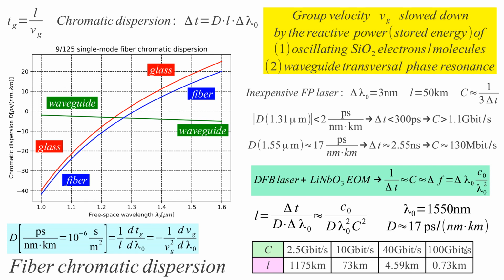And forget 100 gigabit Ethernet with simple on-off modulation. Here we cannot get to our receiver even inside the building. We may have more than 700 meters of cable inside the building. So here it's a real problem. Here we are still far away. 100 gigabits per second is still far away from the 4 terahertz of available bandwidth. But already here the distortion due to chromatic dispersion is so large that it can no longer be used for such communication. We have to resort to different solutions.